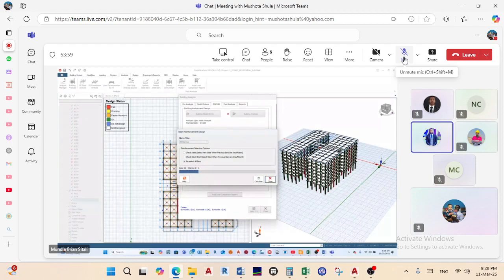That's one of the things that just happened just now. We had a situation where we had a column that is 450 by 450. The cross section has just refused. So even if we try to put in Y32s as reinforcement, it just won't work. So you go back to defaults, adjust your cross section to become something reasonable. Then you can use your steel reinforcement to add in the tension that is required.